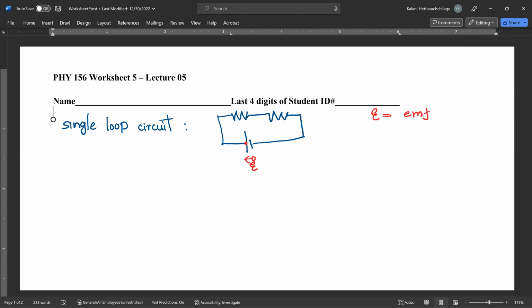But what does that mean? It means I have high voltage here and low voltage here. That's what the battery terminals mean, right? Now, current usually flows from high voltage to low voltage. Because of that, in this circuit I can label the current going from the positive terminal, around, and back to the negative terminal of the battery, right? High and low. Now when the current passes through this resistor, we know that the resistor follows Ohm's law, V equals I times R, right? That means the resistor is going to drop the voltage by I times R.